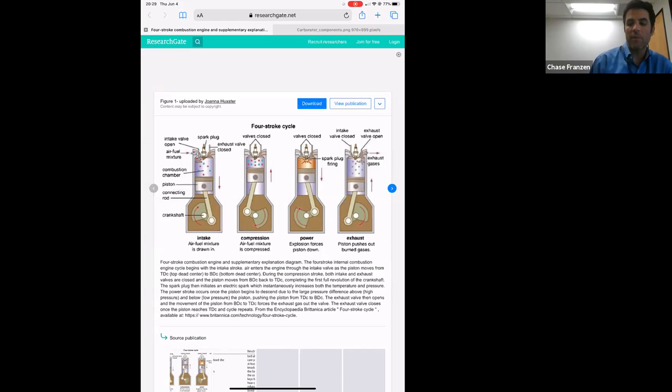So two conditions that we need to be aware of that are bad for the engine: pre-ignition and detonation. At a very simple level, because I do want to move past the power plant and on to some other systems, the idea of detonation is that fuel, like the name says, detonates instead of exploding cleanly and uniformly. A lot of times detonation will be caused by using improper fuel, the wrong octane, if you will.